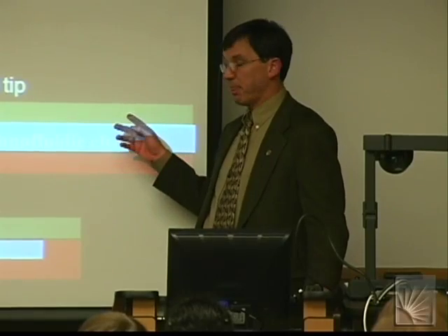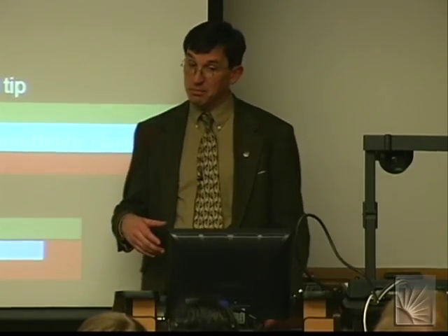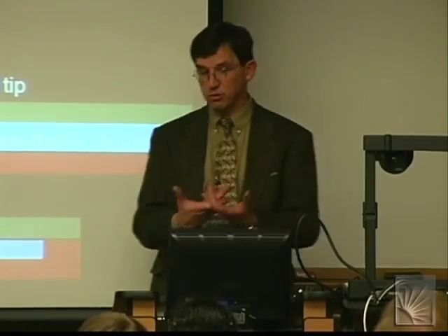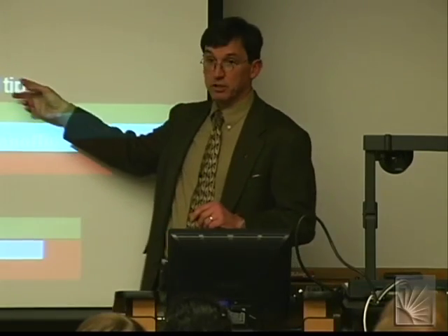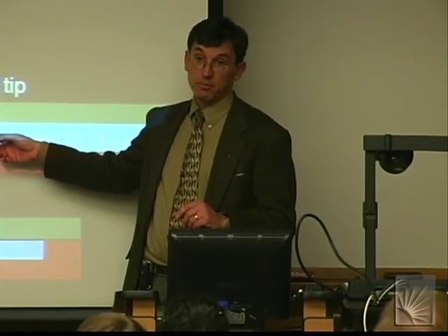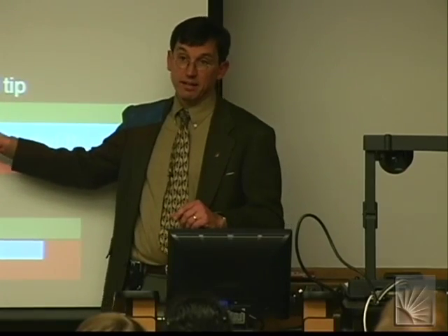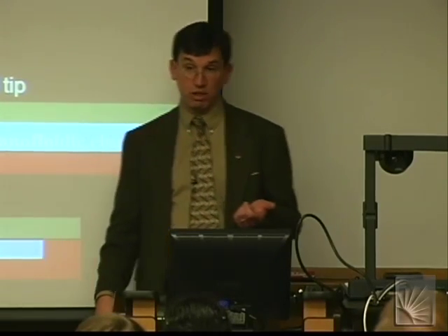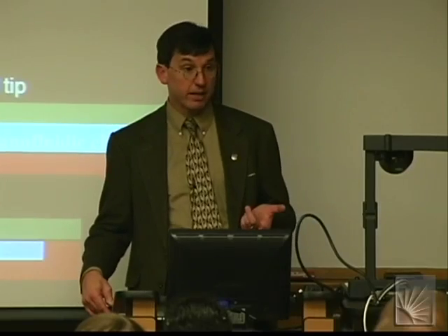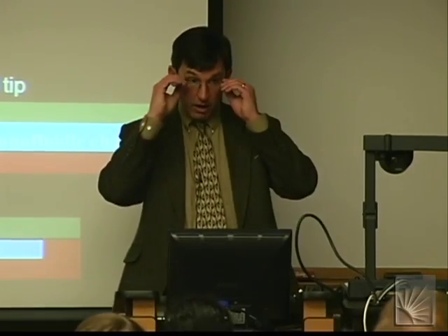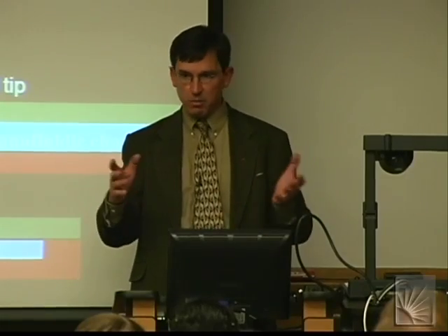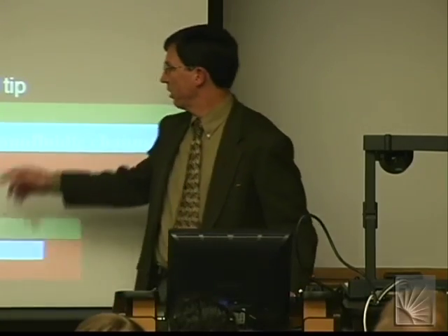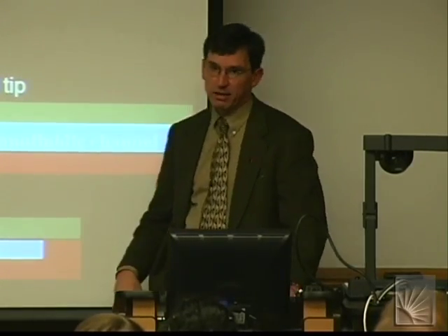The thickness is selected mostly by two factors. We need to make sure that we can get an optical signature through the film, because we have to interrogate the sample, so we don't want it to be too thick. We don't want losses to dominate. The evanescent waves are pinned very close to the surface anyway, and we don't want to lose them through the bulk. That's more important for the cladding layers.